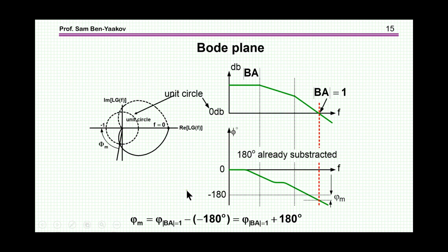The reason is that in order to get a phase margin which is large, like say here, if the cross section will be here, then this means that you'll have to design the system such that the gain, beta A, will be 1 at this point. So this will be the end of the band of the feedback. And beyond that, you have no control. So it will be a narrower bandwidth.